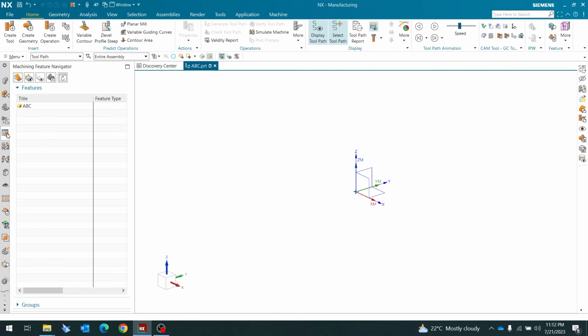If you are having a hole with a diameter of 10 and a hole with a diameter of 10.1, by naked eye when you see, it looks similar. If you are having 1000 or 500 holes, that time it will look similar. Then if you click on those, there might be chances of misdrilling. Misdrilling is nothing but instead of 10.1, if I make 10, then it's a rejected piece.